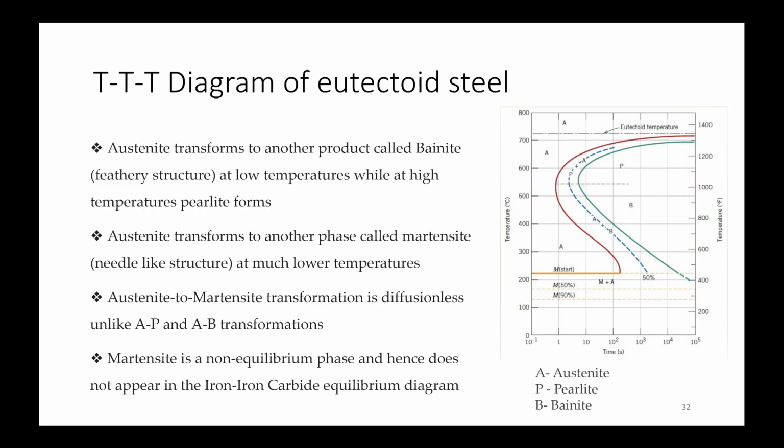Ma'am, in that eutectic system, there was a point that for the pure metal we have a constant horizontal line, and when we are alloying, it won't be like that. In the cooling curve for the eutectic phase diagram, pure metal shows a horizontal line as the phase transformation happens at constant temperature, but we have a T1 and T2 for the other one.